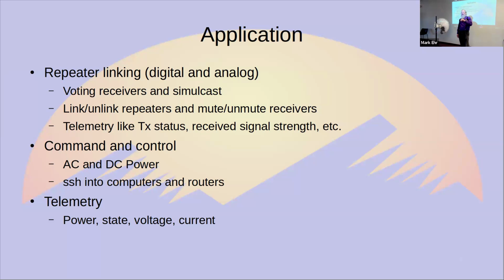So you've got 8 wires in the Ethernet cable, 4 of them are used for power, and 2 of them are used for data. It's a 1 gigabit connection down to the router or whatever is at the bottom. And then at the top here, I'm not going to disassemble it, but there's a couple of SMA connectors, which you then connect to the actual feed horn on the radio or on the antenna using these short coax jumpers. And so basically, this is a completely self-contained unit. You put IP in one side, and you get RF out the other side.